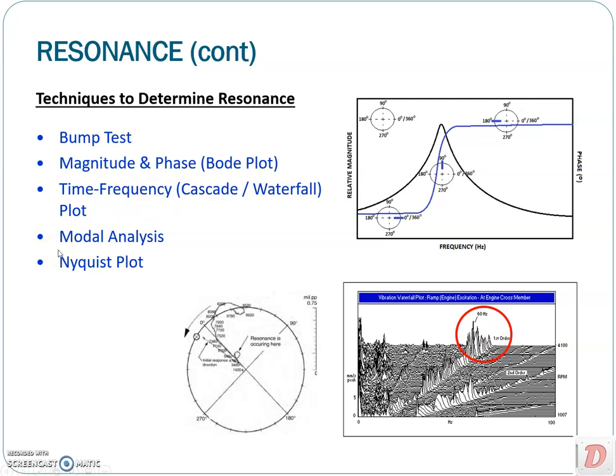Modal analysis is a more complex version of the bump test where a known input force is applied. In this case, the input and output are known, and therefore a full transfer function of the system could be determined, and a more complete analysis could be achieved.